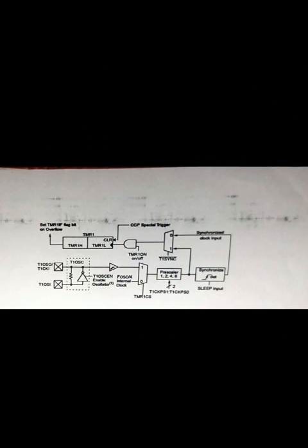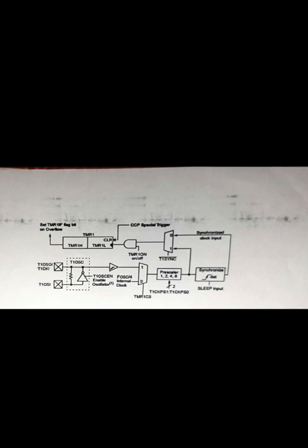External clock can be synchronized or asynchronous. Interrupt on overflow from FFFFH to 0000H. Second crystal permitted. Timer 1 register. Timer 1 has a register called the TMR1 register, which is 16 bits in size. The timer 1 module. T1CON: timer 1 input clock prescaler select bits. The size of the register is 8 bits, and the register is used to configure the timer 1 prescaler and clock source.